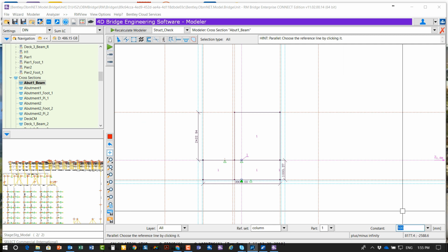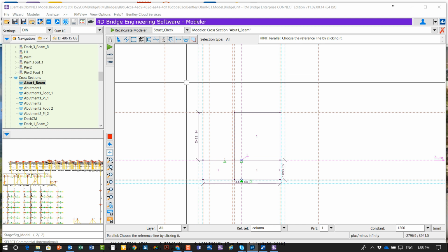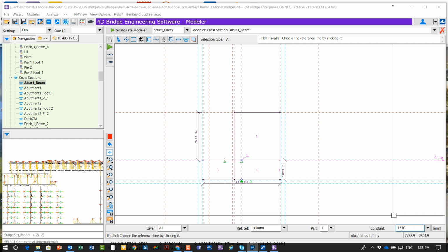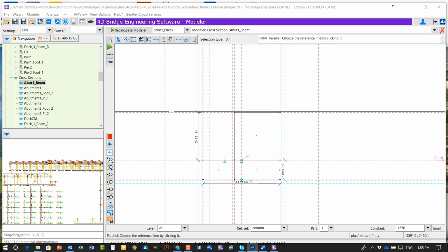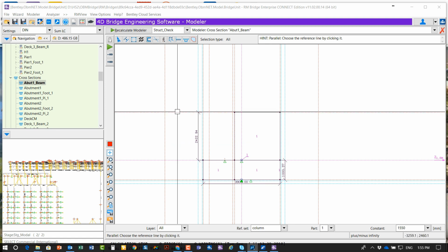So I copy the two construction lines to indicate the size of the beam. Then I copy a horizontal line to indicate the bottom of the beam representing the diaphragm. Then I will indicate with a vertical line where I want my origin to be.